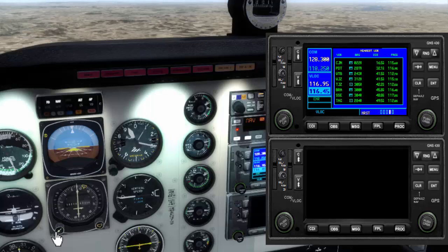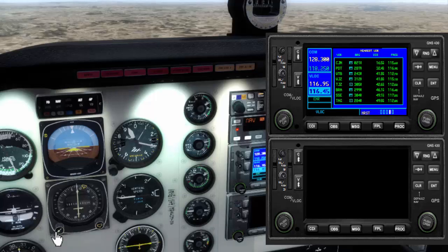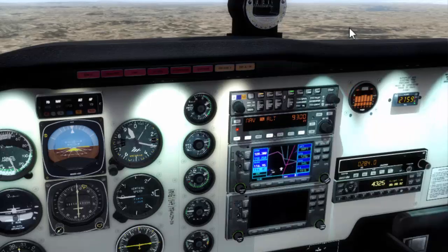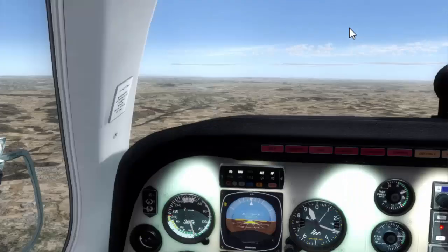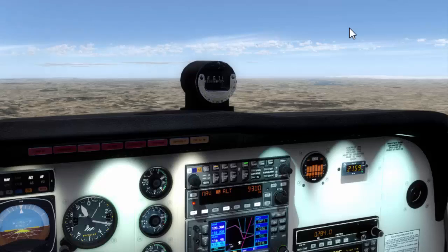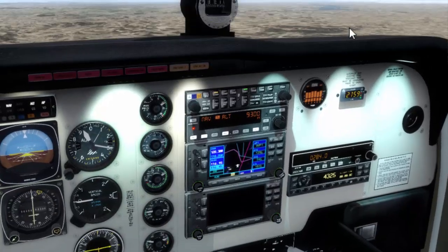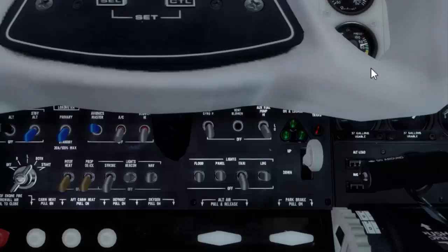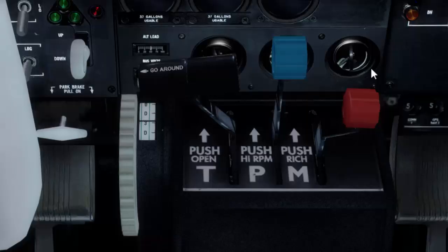Okay, so basically you are listening right now to the Morse code identification of the Perales VOR DME station, which is called Papa Delta Tango. You are listening to it, and of course we are properly following radial 108 from that station, and our goal is to reach a certain point called NANDO, which is at a distance from that VOR of 56.3 nautical miles.